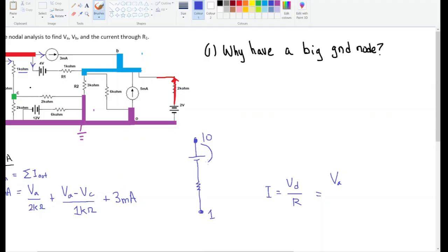From your starting voltage, you subtract the voltage of the battery, which in our case is 4 volts. Then you subtract the ending voltage, which in this case is VB, because the current is going to go through here and go to this B node. What you have left over is the voltage drop across the resistor, right? So in this case, it would be 10 minus 4 minus 1, and that would be 5, right?